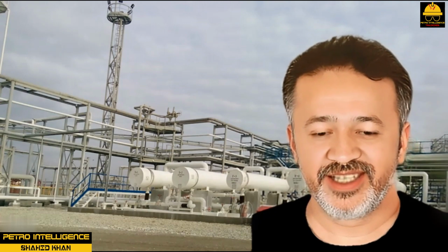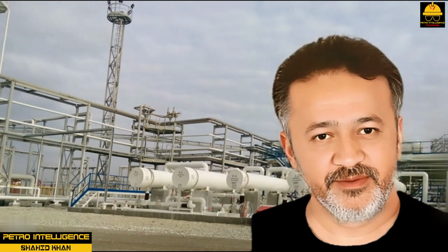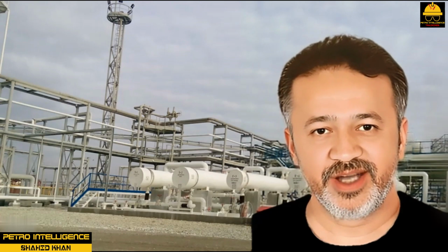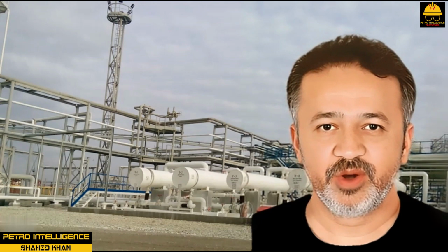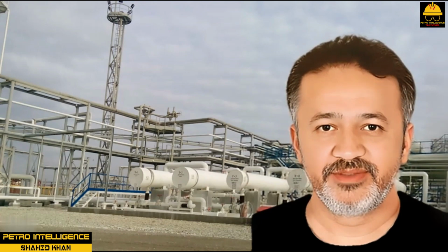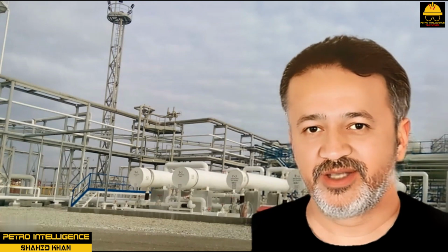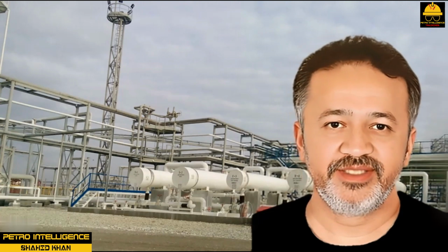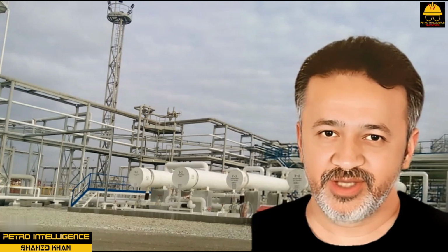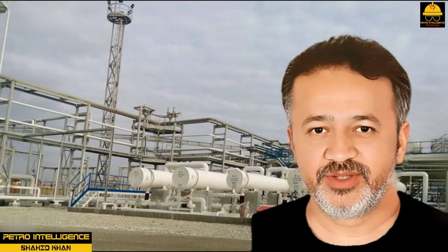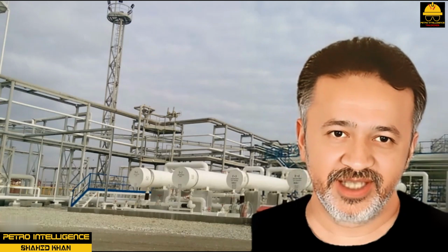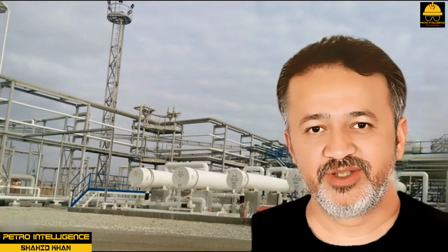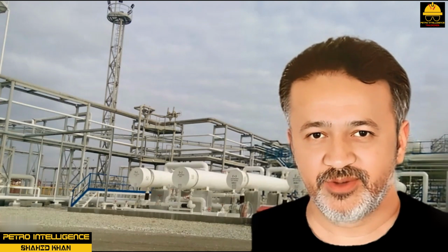Shell and tube heat exchangers are designed to handle high flow rates in continuous operations. Reboilers are used to maintain heat balance in distillation columns. Kettle reboilers and thermosiphon reboilers are the types most often used. Condensers are typically shell and tube heat exchangers often used in distillation columns to condense hot vapors into liquid. The three methods of heat transfer are conduction, convection, and radiation. Conduction and convection are used in heat exchangers, but radiation is not used.